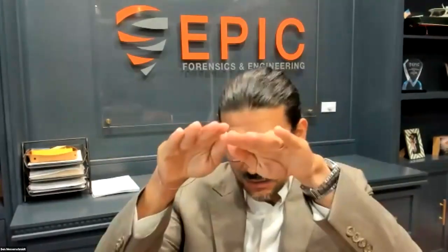So if this is going to be focused on the asphalt leading up to the medians, and presumably those are just going to be your concrete medians, those should be essentially a crown. So you're going to have the highest elevation, and then coming down, if it's going to be a center crown. Part of that design may have a little more asphalt, a little more friction course within there to give you a bit more meat, but it depends on how bad these are getting chewed up, number one. You can even extend out that section of median if you want to provide a little more protection. You may just be pushing the condition farther out.